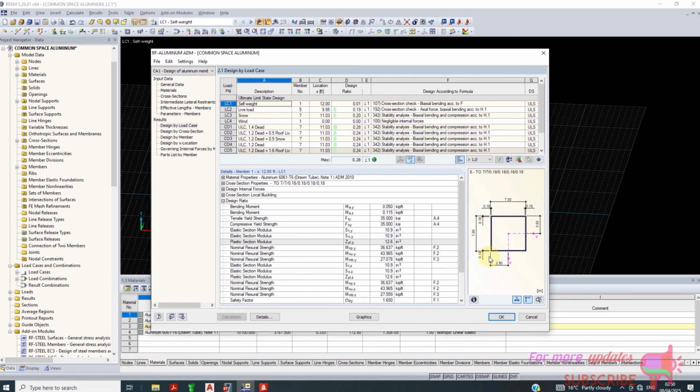Maybe welding, a pure weld connection between members, and I think a very small cross section with a design ratio of about 0.9, the connections there will fail. So I think you should just go with this. Then when you're designing the connections, you're going to check if you should reduce or increase the cross section.